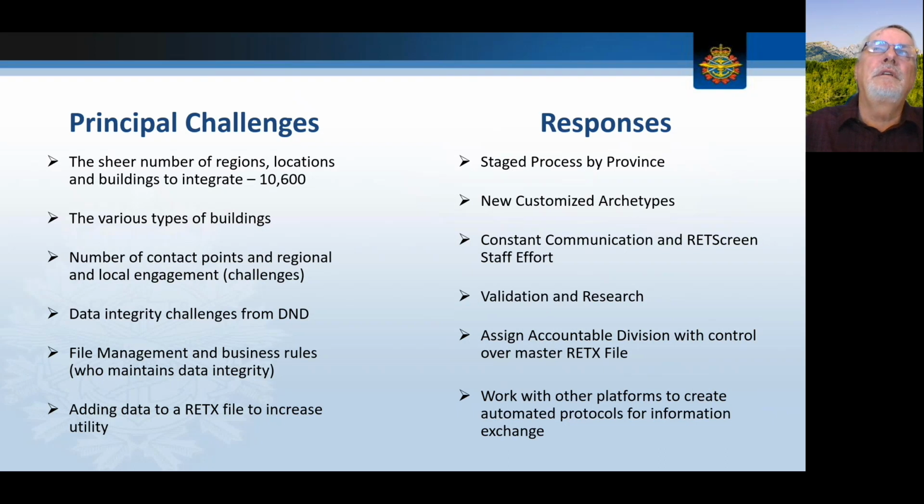So how do we deal with the various types of buildings? Well, we worked with RETScreen to develop some new customized archetypes in the RETScreen software format that match our building styles. Something like a hangar for an aircraft, a fire hall for the military, barracks. Our barracks buildings are quite different. Some of our maintenance buildings are quite different. So we put those sorts of custom templates into RETScreen so that it makes it much more functional for us.